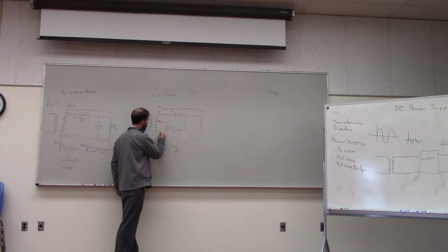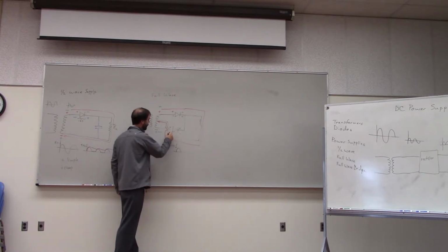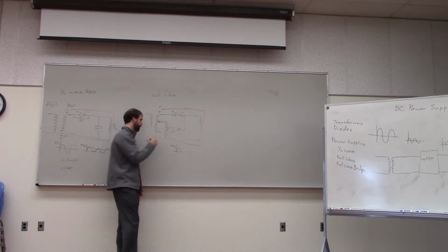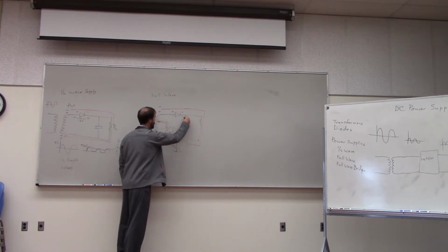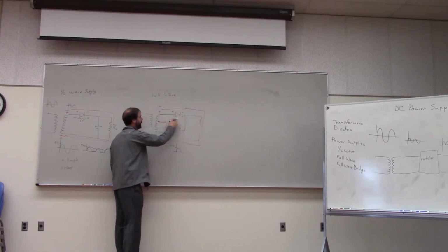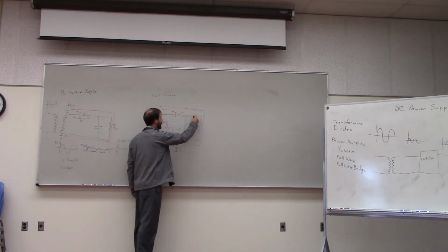So now we're starting off here, and the diodes have voltage like this. So can the electricity go through this bottom diode? Yes, exactly. So it flows along here, comes to this junction up here, tries to go left. Can it go left? No, it's reverse bias. Perfect. So then it comes over here and it goes through the load resistor.